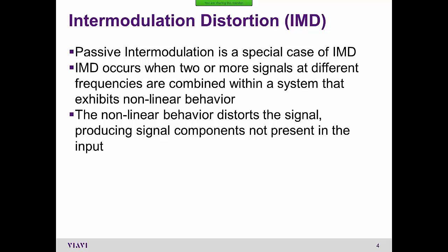And if that system is nonlinear or exhibits nonlinear behavior, you end up with signals that weren't present at the input being generated inside the device itself. And so that's referred to as a nonlinear response. In other words, what goes in doesn't come out. Ideally, in some devices, you want intermodulation distortion. So for example, spectrum analyzers and radios and all kinds of other devices use this intermodulation distortion to their advantage.